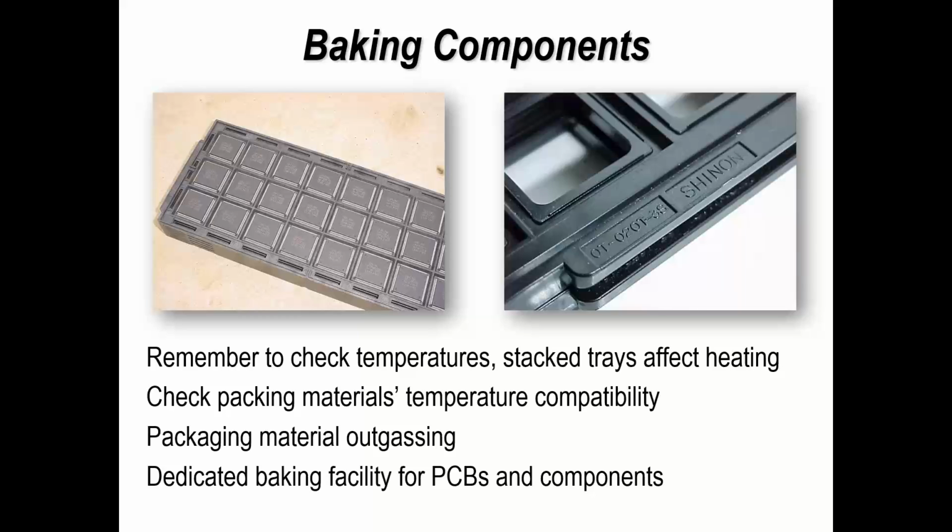But if you're using waffle trays, please check the waffle trays, because just like with counterfeit components, we've also had counterfeit waffle trays, which is kind of surprising to me. But again, it's all about profit in some areas of the world. So just make sure they are compatible with the baking process that you're going to use. And most suppliers would use the same supplier of waffle trays, pretty much all the time. So check the materials that you use for packaging are not going to affect the wettability or solderability of parts if you're going to be baking.